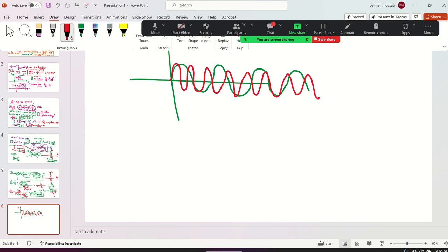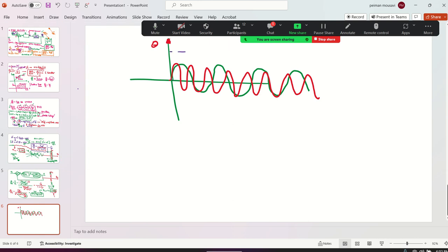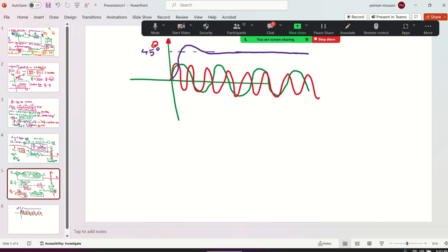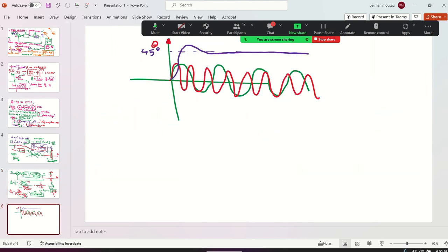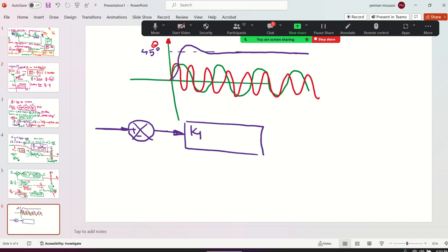Because you want to have this. Your boss said, I want to have this at 45 degrees. Won't you give me this? But you didn't fix the problem. You only added to the natural frequency of the system. That's why I'm sticking to this example, to visualize fundamentally what PID control is. Now you say, okay, boss, give me a second. Let me try a PD controller, proportional plus derivative: Kp plus Kd s to the pendulum. This is going to give you U.